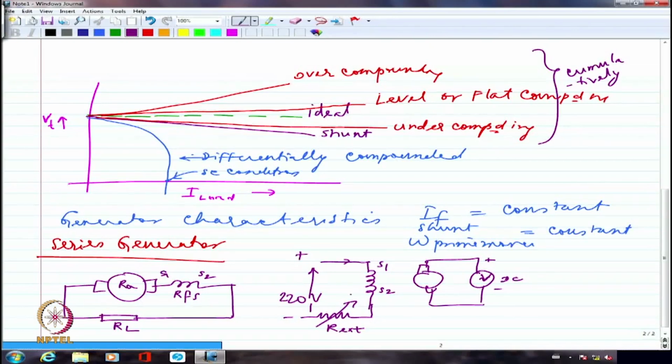So I'm going to have the current that is flowing through the series field circuit. Let me call that IFS, series field current, right? So I can adjust this current by adjusting the external resistance, and I would be able to get an open circuit characteristic even for this. So the OCC will have IFS on one side and EG on the other side. So this is EG. What I'm getting here is EG.